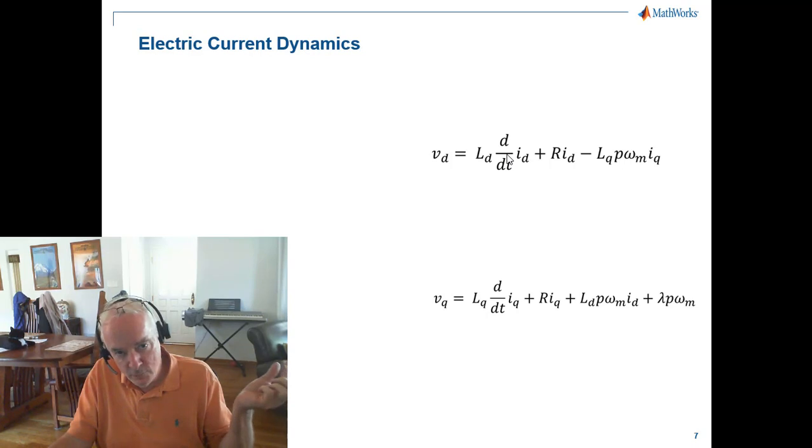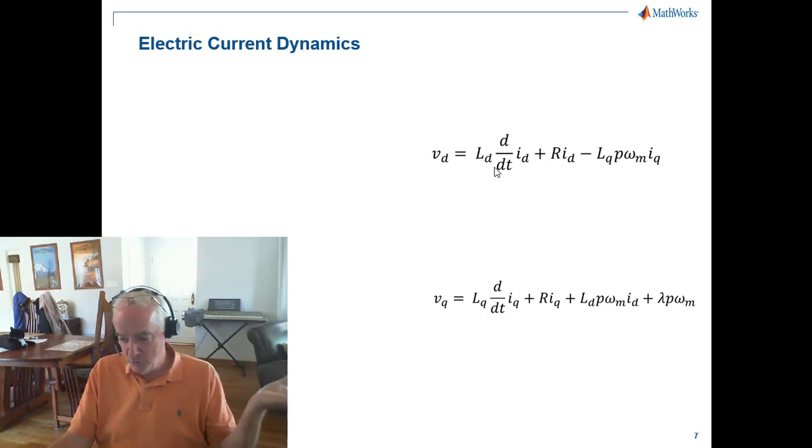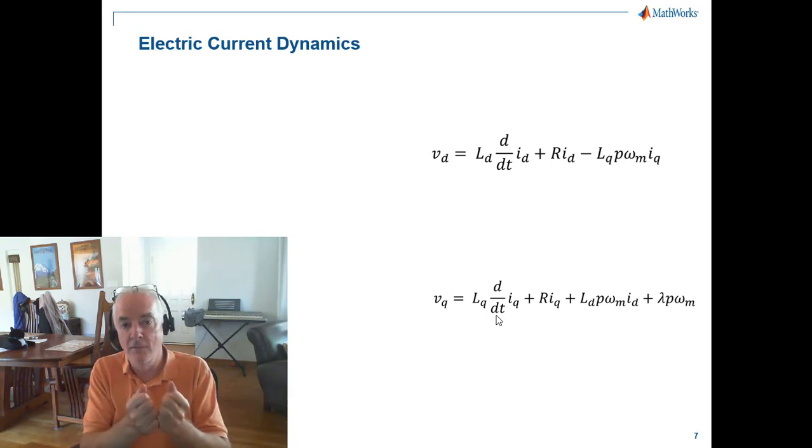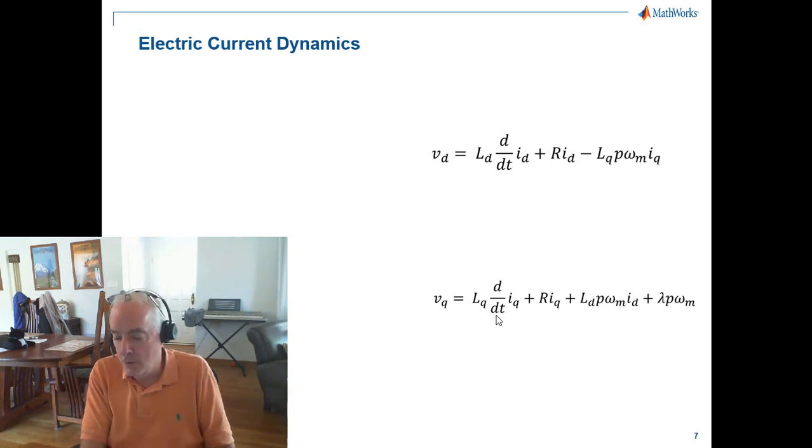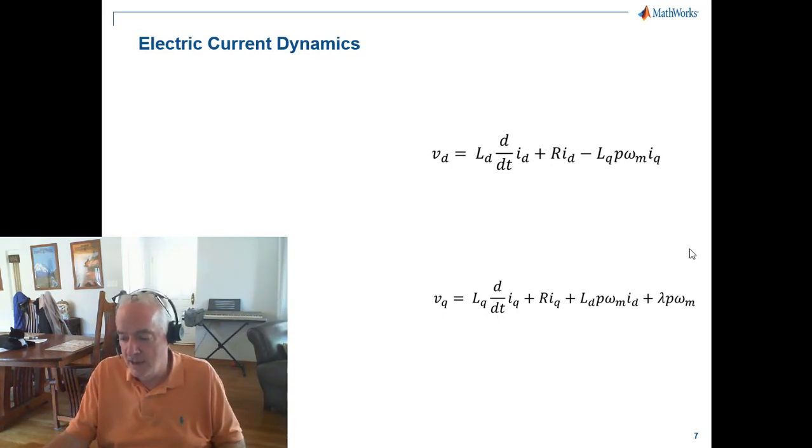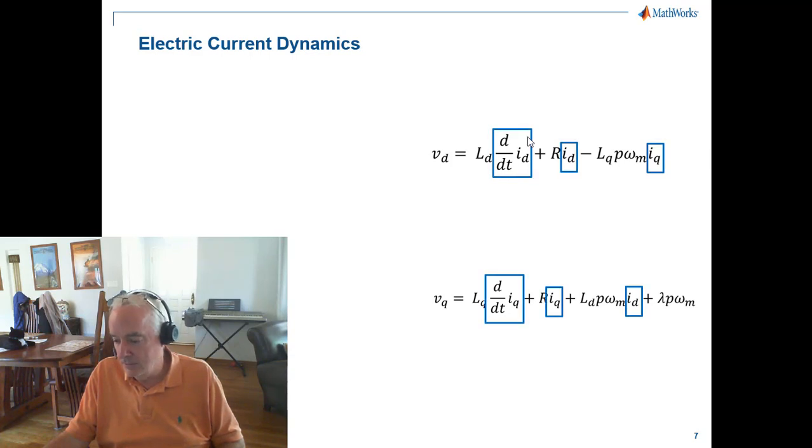And essentially we're no longer solving a differential equation, but an algebraic equation, where we know the derivatives because we have a very good understanding of what the system is and what we want it to do. I said we want ID to be 0, therefore its derivative will be 0. That simplifies this equation tremendously. So it turns out for our motion command that we know everything we need to know about IQ also.